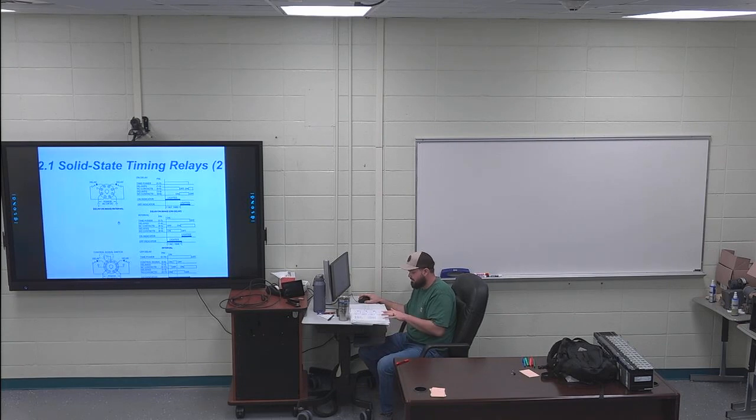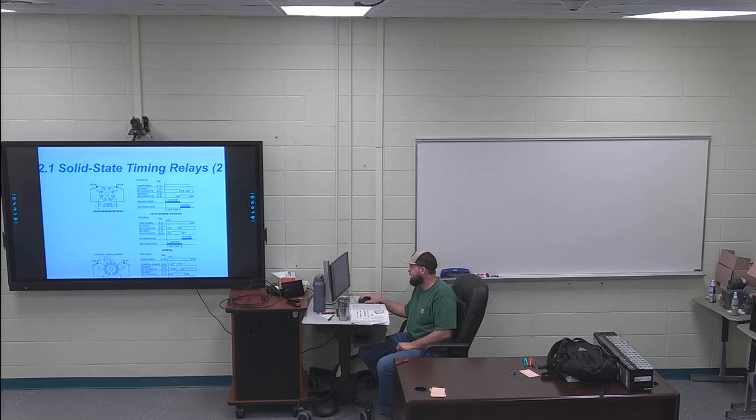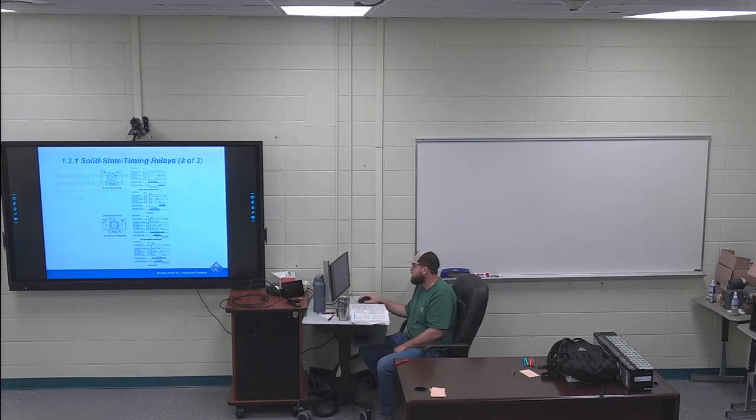This is from section 121, the solid state timing relay. You can see this is a plug-in timing relay, and then this would be like the back plane. You're going to have a question on which ones are your normally closed contacts. So if I'm looking at this, I can see this is my normally closed contact, so connecting from 1 to 4 is normally closed, and then from 5 to 8 is also normally closed. You'll have that as a module review question. You've got the section 1 review on page 13. I'm going to continue on to section 2.